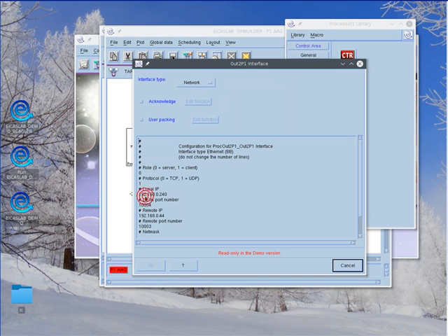For this interface, the local IP is the address of the board, and the remote IP is the address of the device of the EICASLab RCP platform used by the interface that receives the data sent by out to P1, and which is represented by the in1 block that we have just shown. Note that the sending and receiving port numbers correspond to the ones indicated for the in1 block.